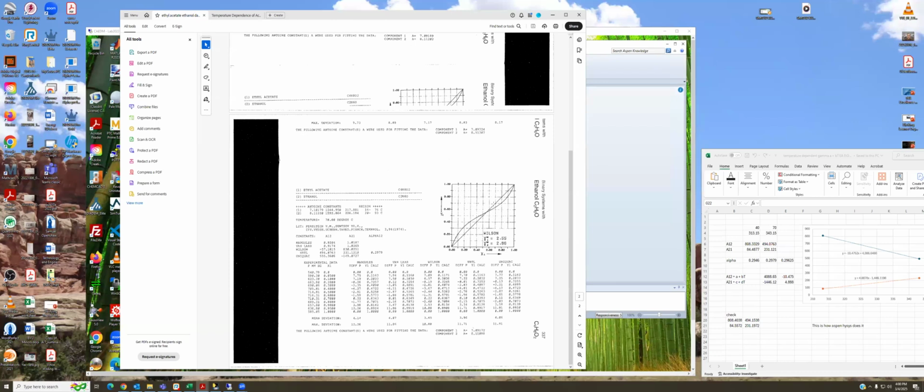that means the feed will be over here. Then the top product again will be the azeotrope, but at this composition, and the bottoms will be pure ethyl acetate. So if we can do this separation, we'll have two product streams, pure ethanol and pure ethyl acetate, and the azeotrope streams will be recycled internally, and so we'll have no off-spec product. So let's see if we can do that.